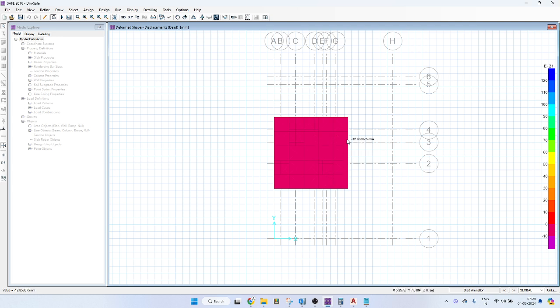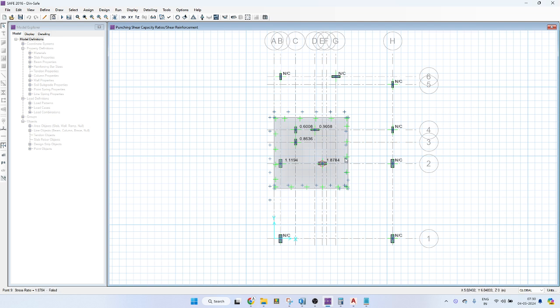Now see, it's within the permissible limit. Previously, what was the problem? We had to increase the size. Increasing the size and increasing the depth should happen proportionately. People will comment on both, like they'll say the size is too high, but you can't do anything because you need to try to bring down steel also. Concrete is cheaper.